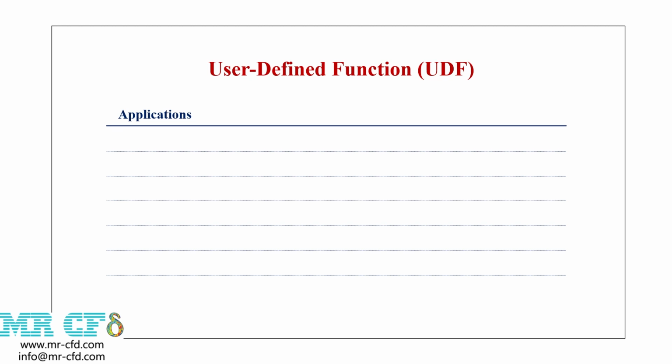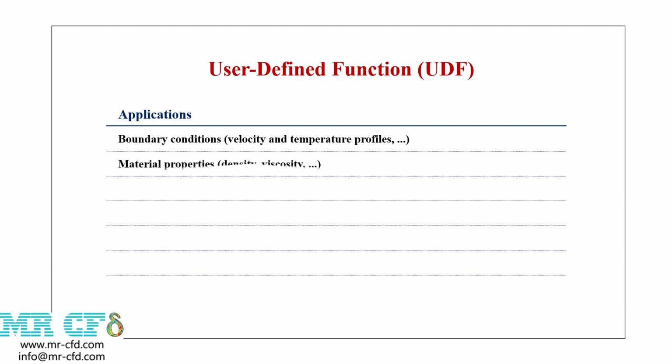Using UDFs for specific boundary conditions in the problem such as velocity and temperature profiles etc. based on location or time. Using UDFs to define the thermophysical properties of the fluid such as viscosity and density based on a specific relationship. Using UDFs to create source terms in governing equations like a source term in momentum equations or energy equation.